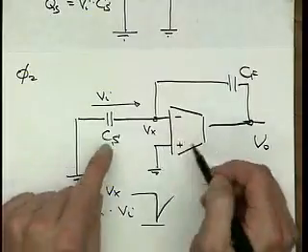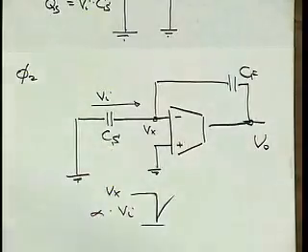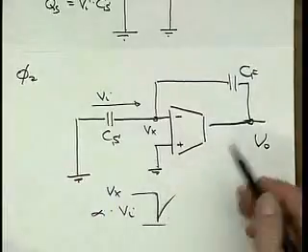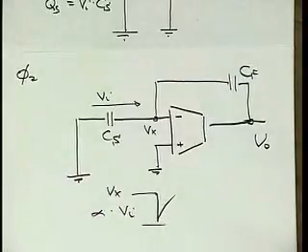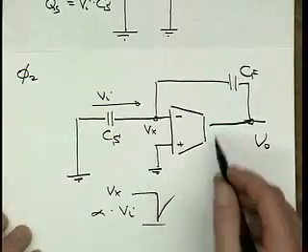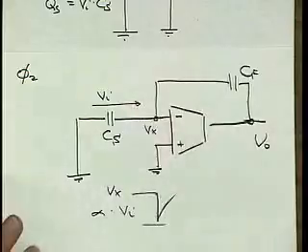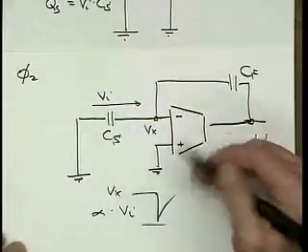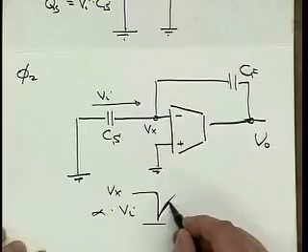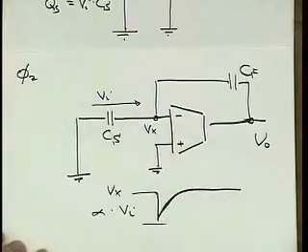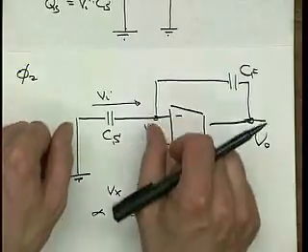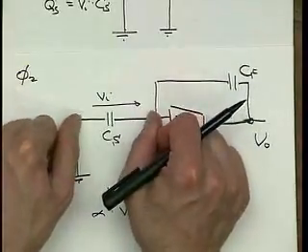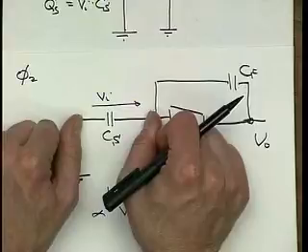But then the amplifier gets in gear. And why does this happen? Well, because the amplifier is relatively slow compared to these switches, which instantaneously yank the connections around, right? But ultimately the amplifier, if the feedback loop is stable, will restore the virtual ground here. So what has to happen on this Vx is that it has to go back to 0.